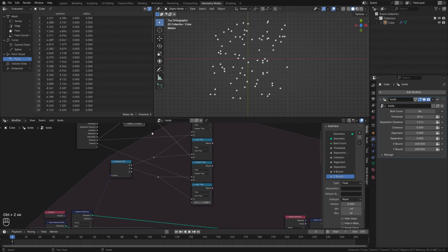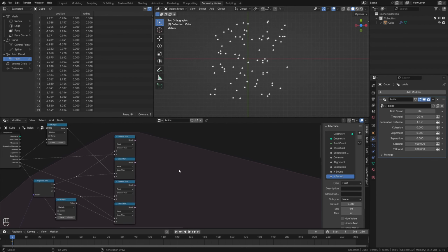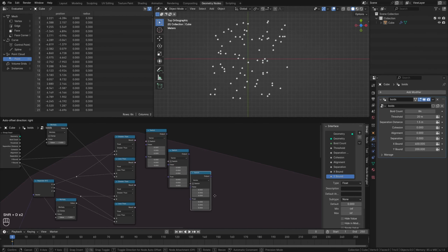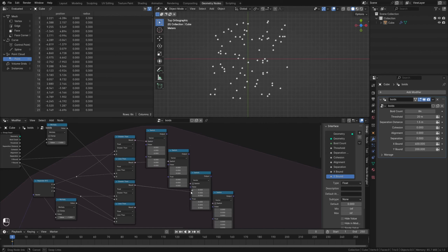Now, the boundary is user editable, and we can tell when a Boid crosses any of the boundary lines through the compare nodes. In order to translate these Boolean results to a vector output, we will again make use of switch nodes. Add 4, all set to vector. Connect them horizontally from the compare nodes. Leave the false vectors unchanged, and for the true vectors, use the following.